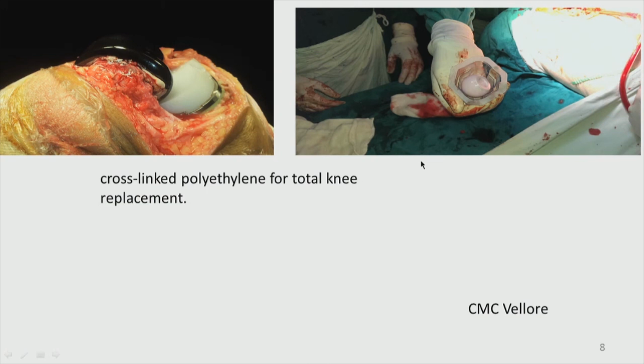So, we have cobalt chromium metals, okay, cobalt chromium molybdenum. So, we have the rotating ball and socket like, and so polyethylene finds application there because they do not want to have metal on metal, that is both ball and socket being metal on metal. They have one of them as polymer. So, the attrition rate will be much less, whereas metal on metal could lead to a lot of metal debris.